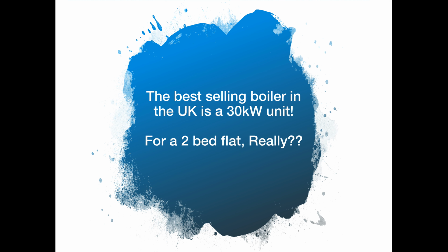This is where it starts to get quite interesting. We could see that last project had 135 flats. They worked out at 40 kilowatts per unit, and that's what was being supplied by the boilers. This is the fact: the best-selling boiler in the UK is a 30 kilowatt unit. Now I know everybody's going to say yes, but that's designed on hot water, which is absolutely fine.